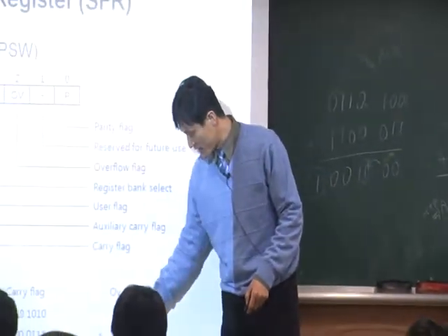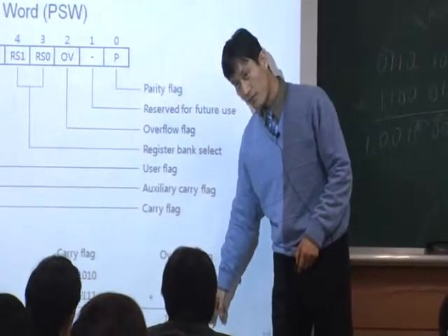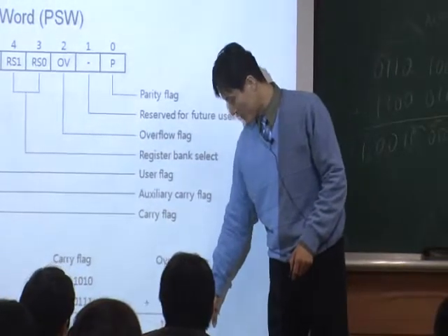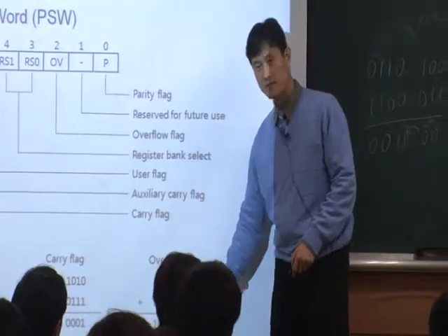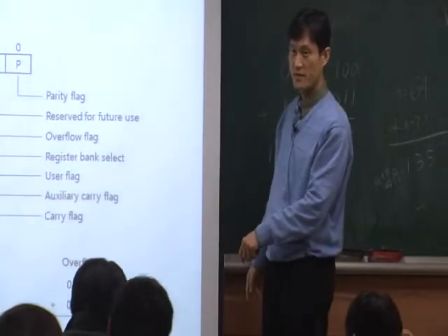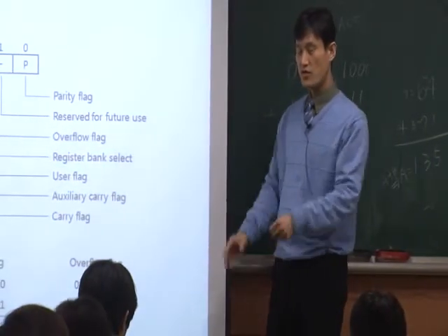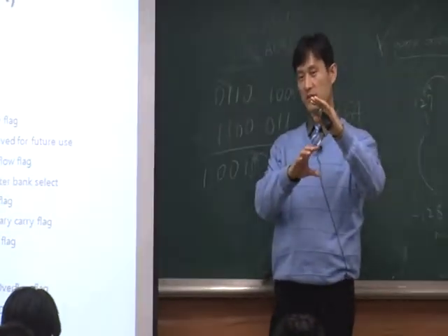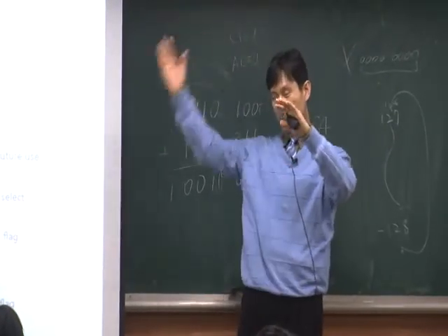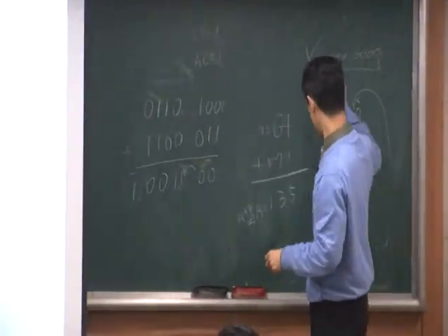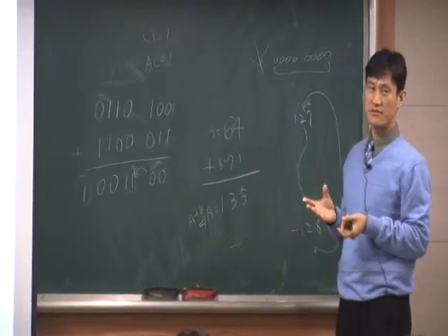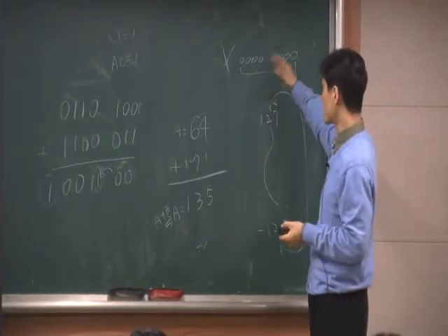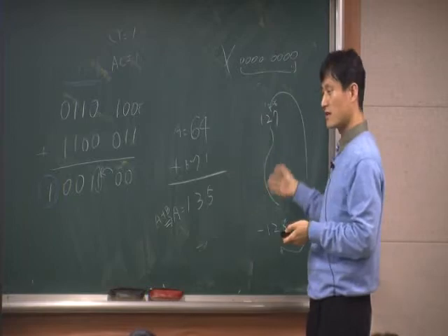When you do the binary addition, this is the output, but this output actually is a negative number. So you are adding two different positive numbers, and it's rolled back and becomes a negative number because it overflowed. That's overflow.